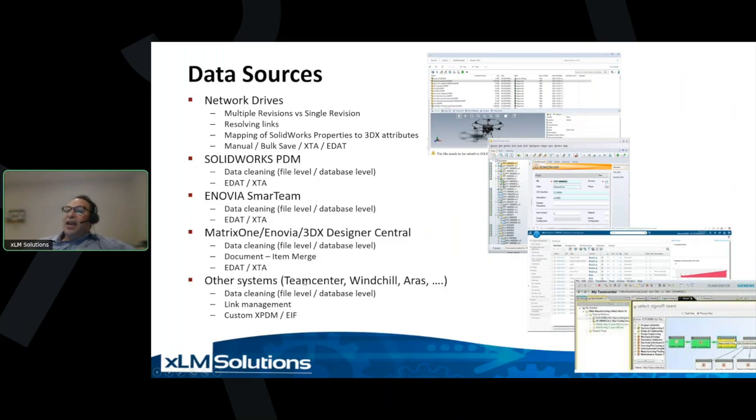And then if your data is in another system, a more complex system like Teamcenter, Windchill, Eris, whatever, again, you may need to do some data cleaning. You may need to work on link management, making sure references all match up. But there's also technologies from Dassault that can be used, XPDM for on-premise and EIF for on-cloud, to get that data into 3D experience.